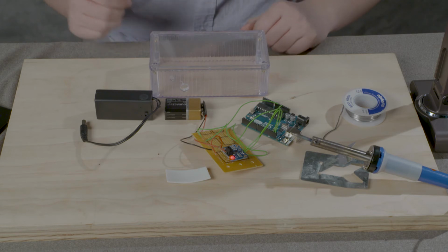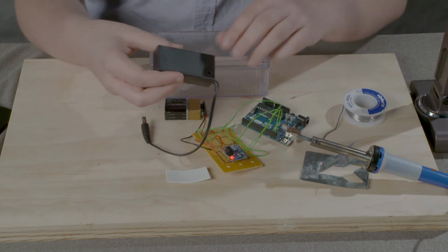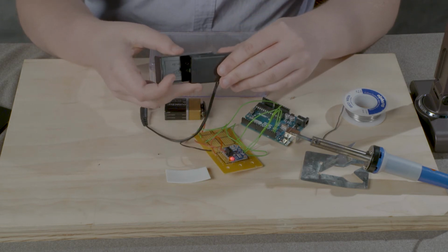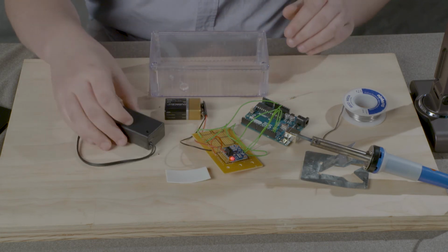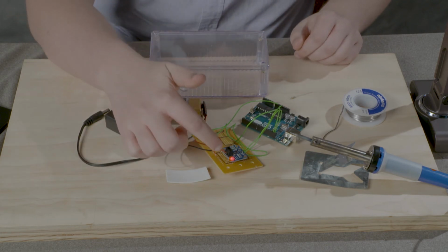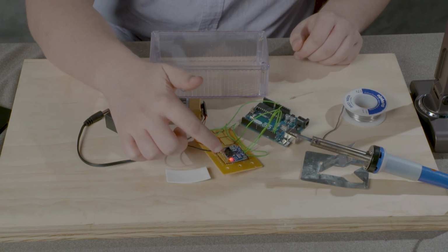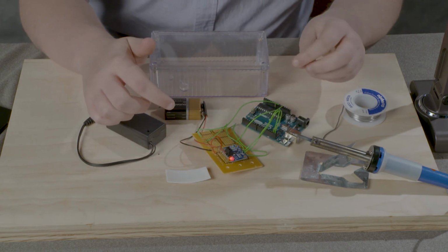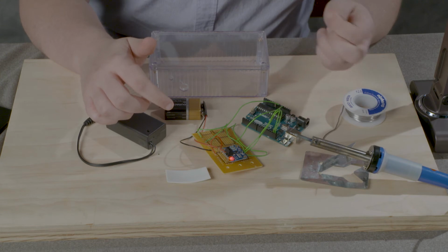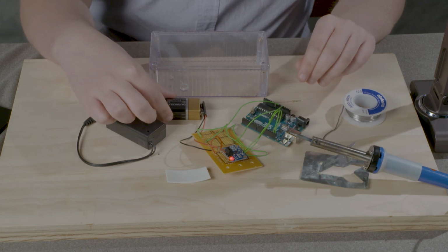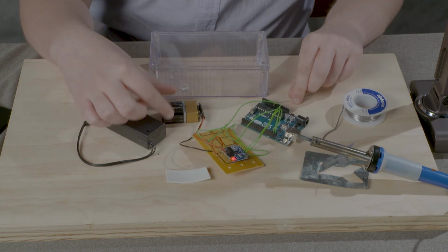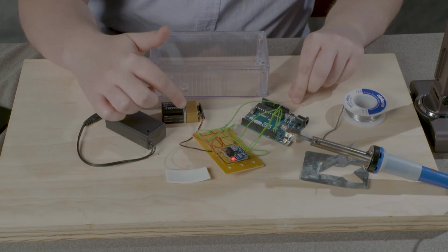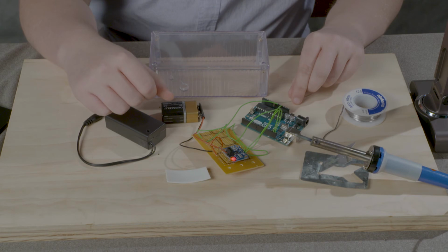In this activity, we're going to be putting the 9-volt battery holder onto the case. We're also going to change the resistor that we have here from our last circuit with one that's around 4.7 kiloohms. The last thing we're going to do is solder and remove the 9-volt battery, because later on we're going to be swapping this for a solar panel.